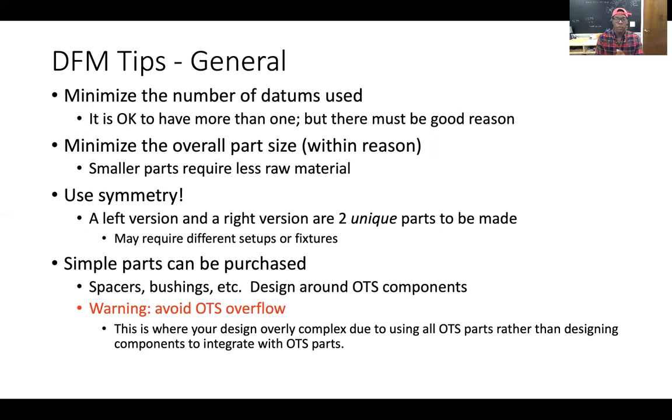So I zero off on one side and I can find all the features, boom, I'm done quickly. But if there's a datum here and there's a datum halfway through and there's a datum 3/4 of the way through, now I'm having to measure all of these different places. It's taking me forever to find your features, and that costs money. And so we want to minimize the number of datums that we use and make sure that we have optimized that to the best of our ability.